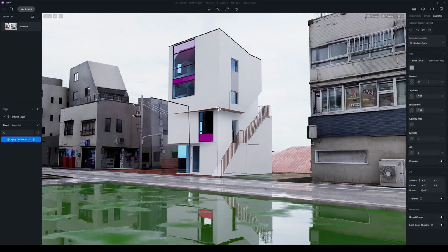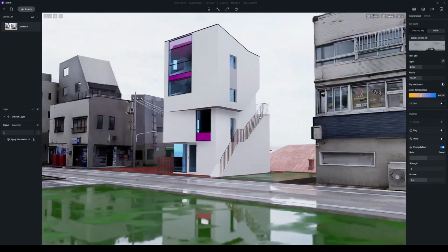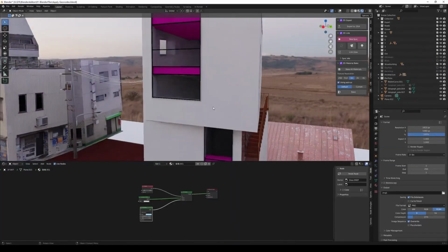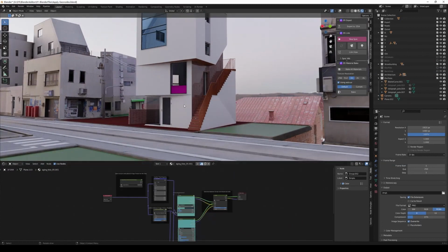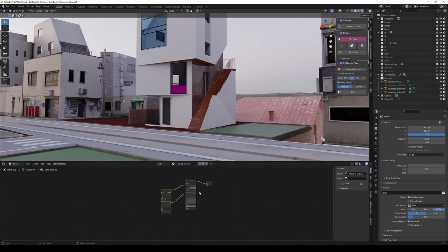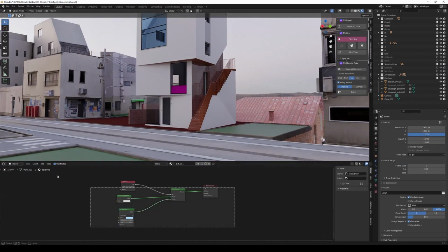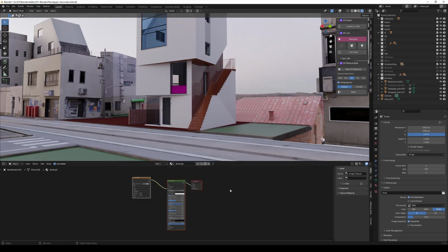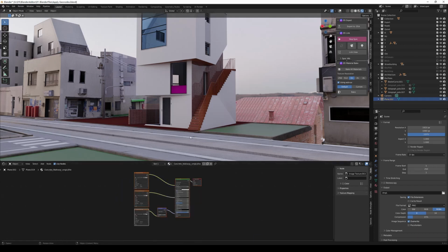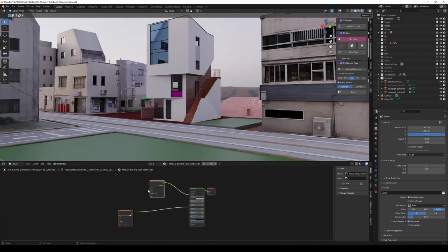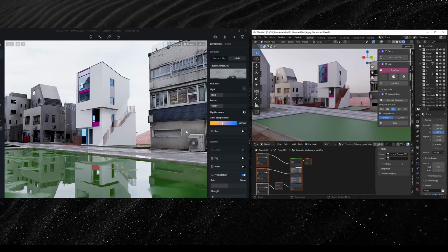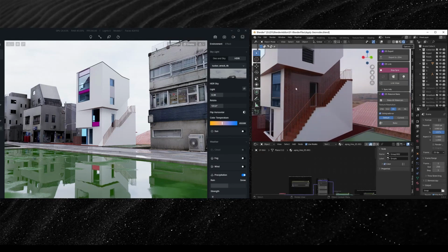Next, let's adjust the materials for a more realistic rendering. For now, D5 Converter Blender supports the material mapping of Principled BSDF, Glass BSDF, and Diffuse BSDF. Materials of these types can be synced directly from Blender to D5. To highlight the red bricks and tiles paved on the building facade and stairs, you can use procedural textures to blend the materials in Blender.